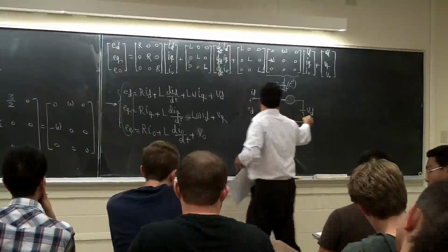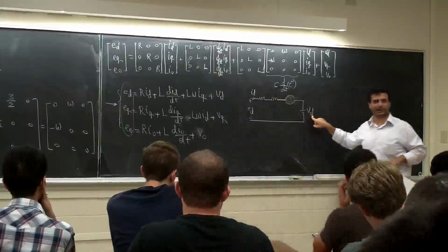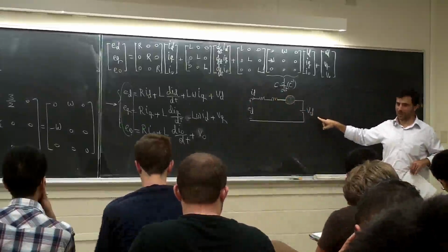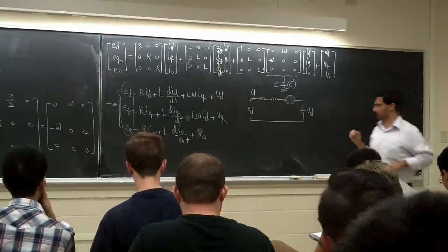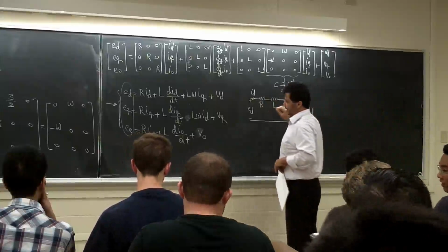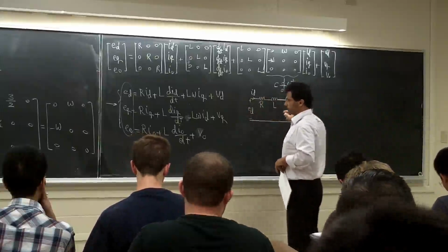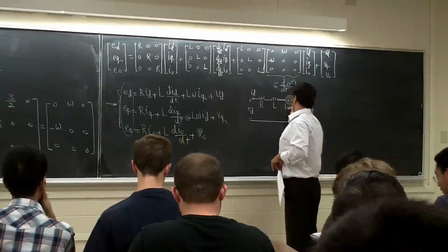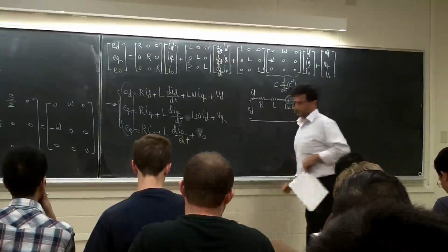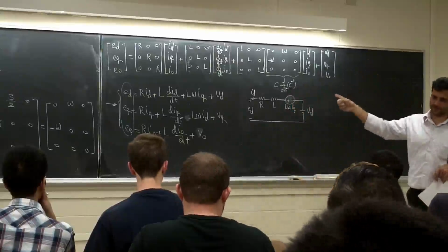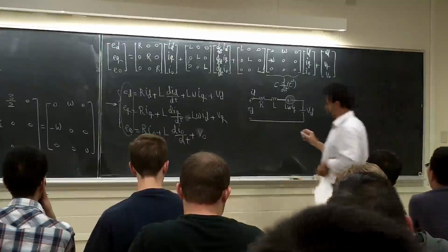Say this is a V_D, I put a DC value. It's going to be a constant number from now on. This one is going to be a constant number. This is R, and this is L, and this one is plus. This is L omega I. This is the equivalent of that circuit, ABC in the D axis. Q axis is going to be like this.